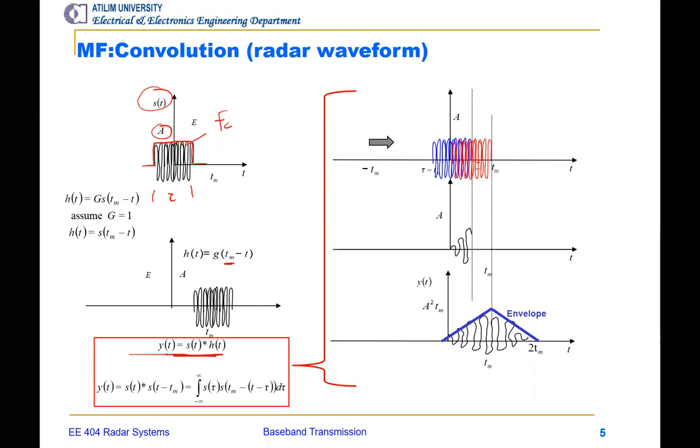If we try to visualize this, we just take the input signal and then sweep it from minus infinity to plus infinity by the amount, which is simply denoted by tau. So for every new tau value, we look at the input signal and the impulse response of the filter and determine the overlapping area, and then get the output signal.